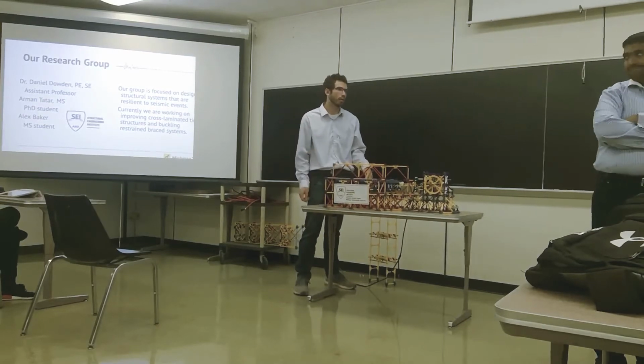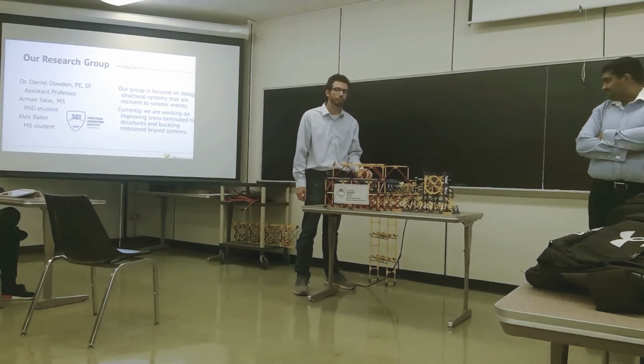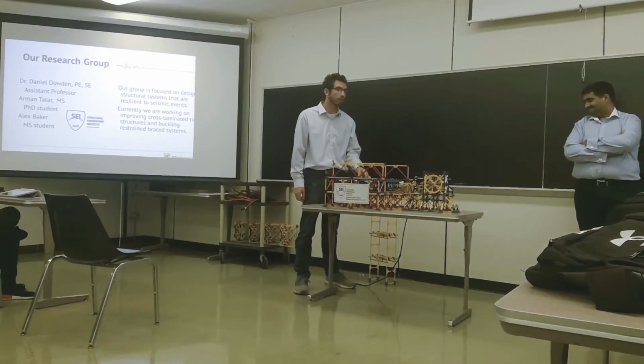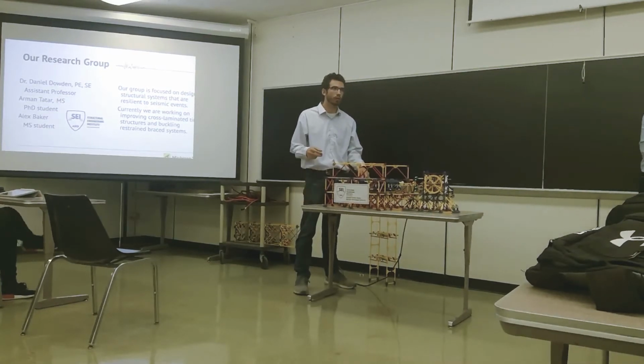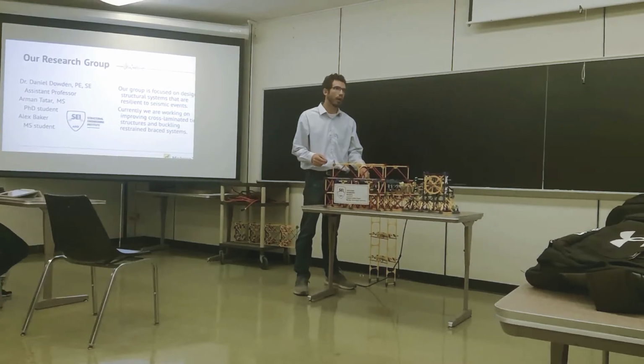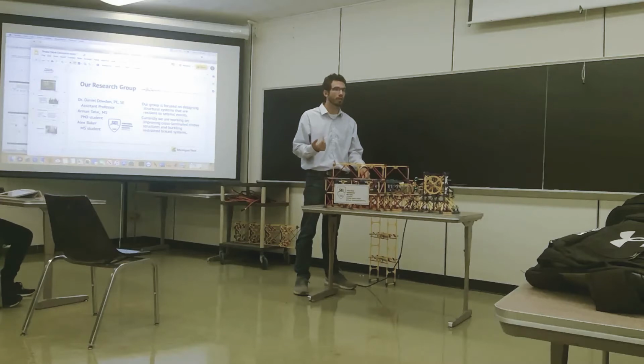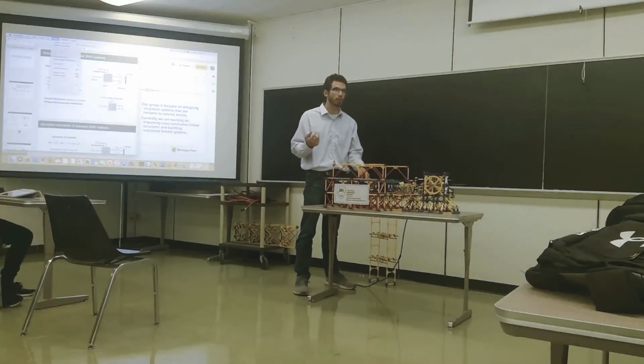I can answer that a little bit. So referring to decaying over time, if you have a steel beam or something, the decaying over time would really happen from deterioration such as rust, but if you're in a building and it has rust protection, that's probably not going to be as much of an issue.